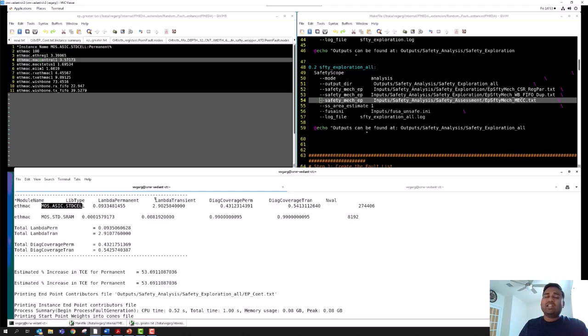So we can use these tools in two ways. If you are concerned only about running a fault simulation, optimizing your fault simulation exercise, choosing your safety mechanisms correctly, inserting them, and then running the fault simulation exercise, you can use these tools in batch mode, and it does a pretty good job of providing the information through these text reports and log files.